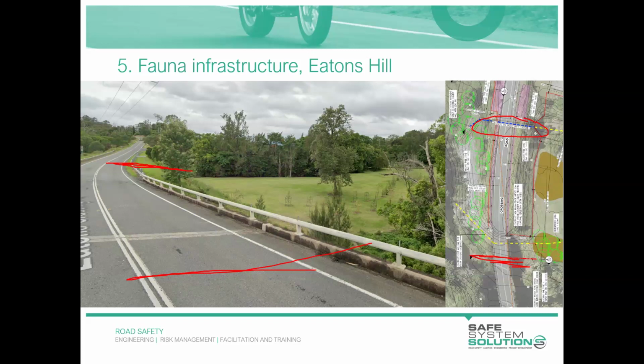The control measures we came up with were to carry out most of the installation works on the ground before raising it in place, and using harnesses when working at height, and or using elevated work platforms like scissor lifts, etc. This reduced our risk to low, having a likelihood of unlikely and a minor impact.